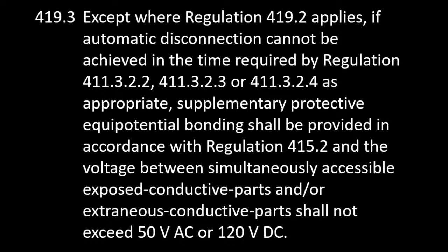So yeah, it's a regulation. It was one of those real light bulb moments when somebody showed me that regulation, because otherwise you kind of think, oh, I'm stuck. If the DNO can't help me, if I don't want to put an RCD up front and they won't accept me downrating the fuse, I'm kind of stuck. And that regulation allows you to have a third option, which is really useful.